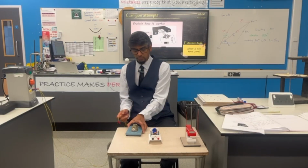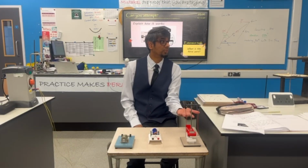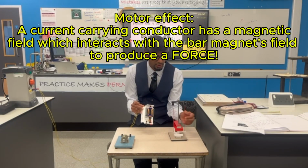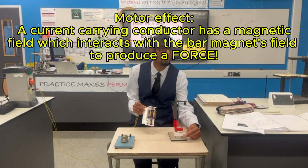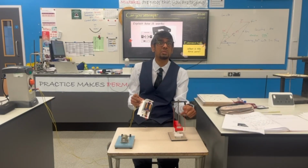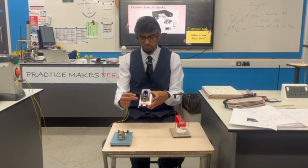So in order to understand the DC motor, it's called the DC motor for a reason, because it uses the motor effect. So we know how we had the current carrying wire in a magnetic field experiencing force. You saw it was moving one way, which we can predict using Fleming's left-hand rule. In our last lesson, remember, when we swapped the current, what happened to it? It went the other way. The same here.